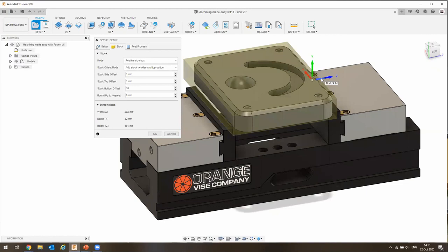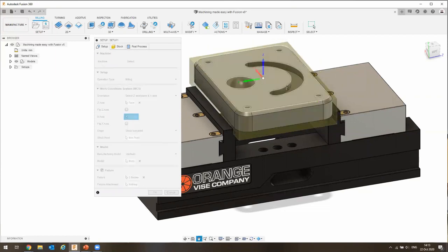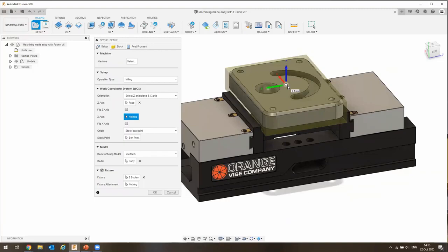When you work with normal 3-axis CNCs, your X and Y is the bed movement left and right and back and forward, and the Z is the head. So it thinks the cutter is coming from the right-hand side. Now, if I hit the arrow, it will go the other way. And if I click on the little axes, I can actually click on a face and the part will invert. What I want is the Z to be facing up. I'm going to go on the corner.